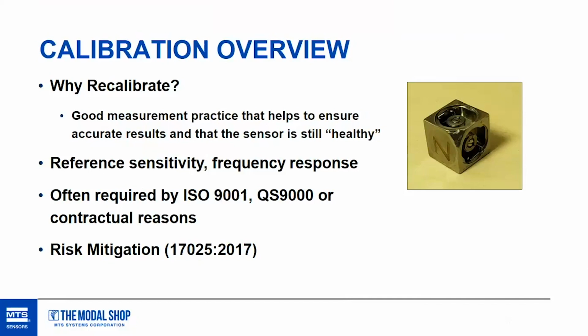The famous example I always like to give is Joe, technician, out there working on his system, and he needs to pull these sensors off to rearrange them. Without much training, someone tells him, hey, go up there and grab those. So Joe grabs a flathead screwdriver, uses it like a chisel, and bangs on the bottom of the handle to pop off an adhesively mounted accelerometer. In almost all cases, that is going to gouge the bottom of the accelerometer and oftentimes the structure a little bit as well. But for the accelerometer, damage to the base is the number one failure mode.